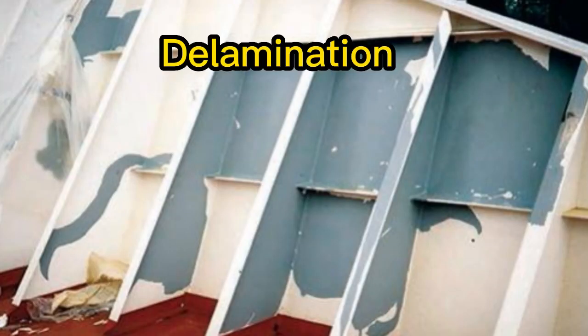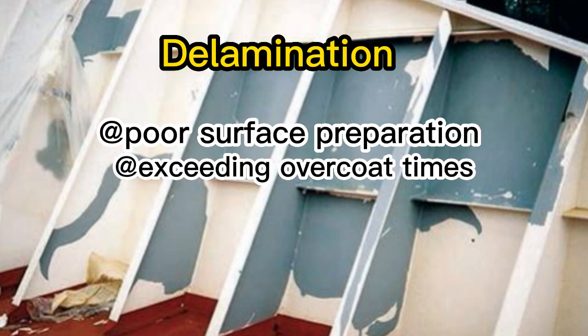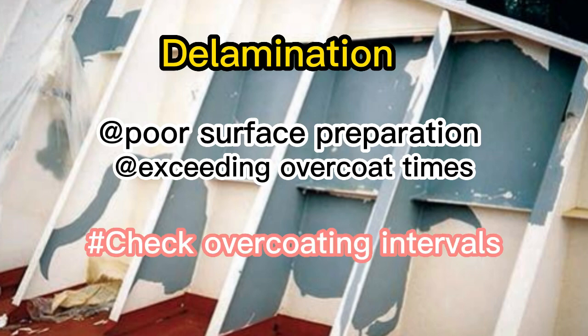Delamination is caused by poor surface preparation and application defects, such as contamination between coats, exceeding overcoat times, or application to a glossy surface. To prevent this defect, ensure that no contamination occurs between paint coats. Follow the recommended overcoating intervals and lightly abrade and clean glossy surfaces between coats.